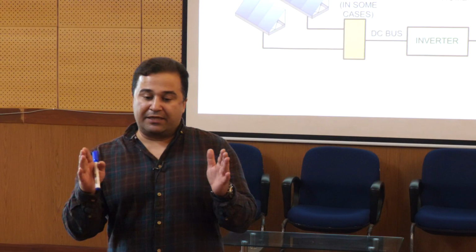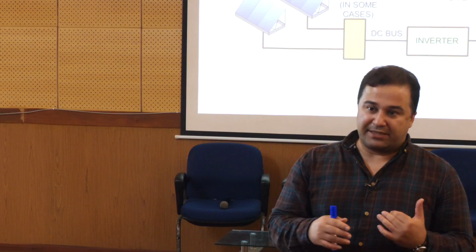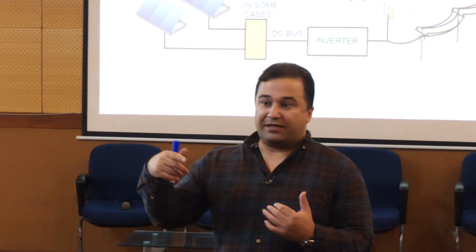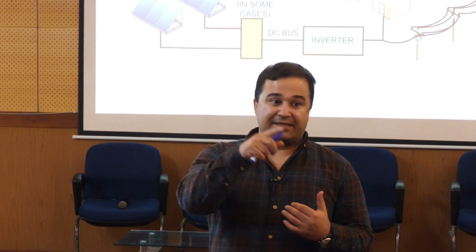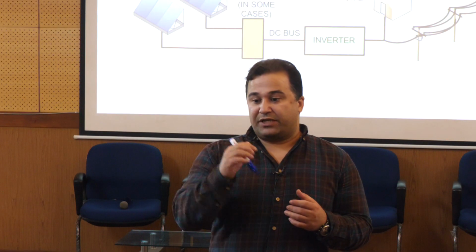So assuming we have an AC and a DC. We use AC, but it has induction losses, because Z in a cable is R plus jLω. So we have this voltage drop and losses also. But when we go more than 80 kilometers, the price of the power which can be saved is more than the price of the converter.